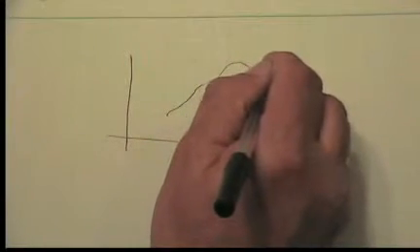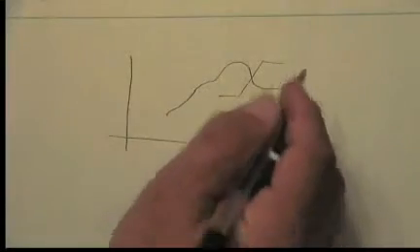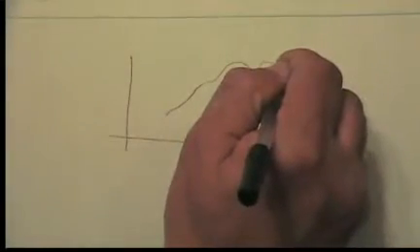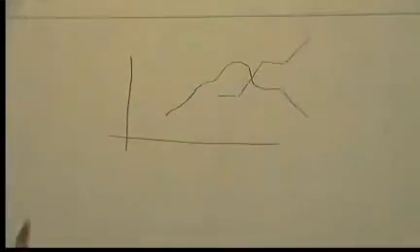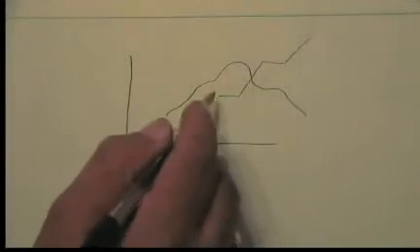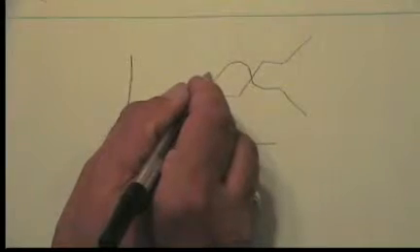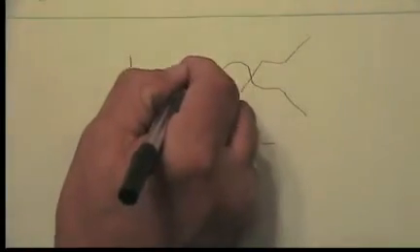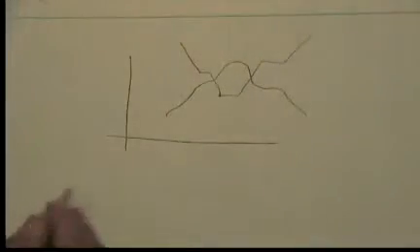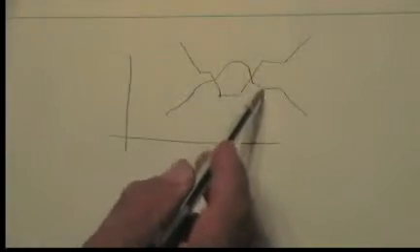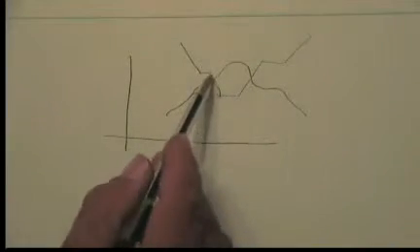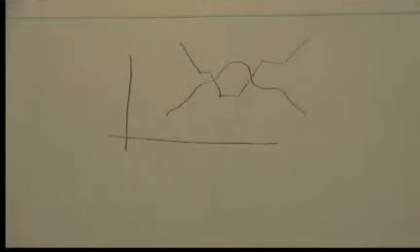It's going to flatten out. That corresponds to a fairly flat period here. And then it's going to rise up again to compensate for this fall. Same thing on the other side. It's going to rise up, flatten out briefly, and then rise up again like that. And you'd have to measure the actual slope of this original line to approximate what multiple of 20 dB per decade rise or fall you'd have for this.